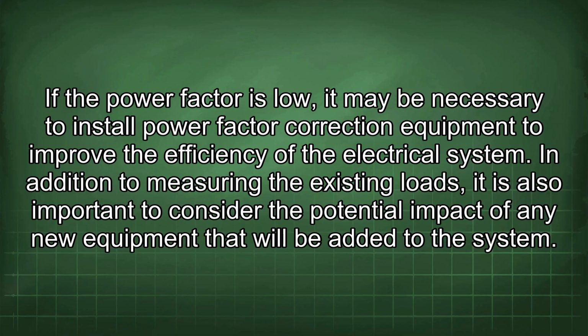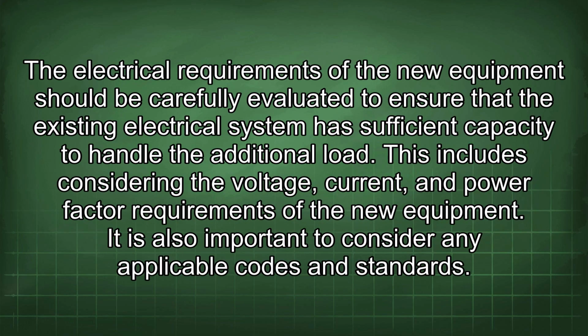of the electrical system. In addition to measuring the existing loads, it is also important to consider the potential impact of any new equipment that will be added to the system. The electrical requirements of the new equipment should be carefully evaluated to ensure that the existing electrical system has sufficient capacity to handle the additional load. This includes considering the voltage, current, and power factor requirements of the new equipment. It is also important to consider any applicable codes and standards.